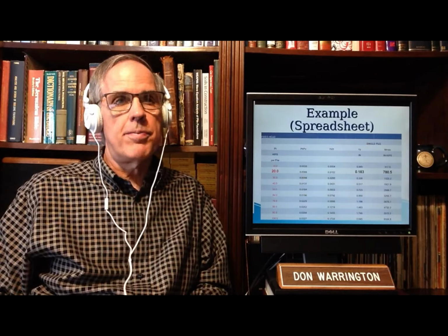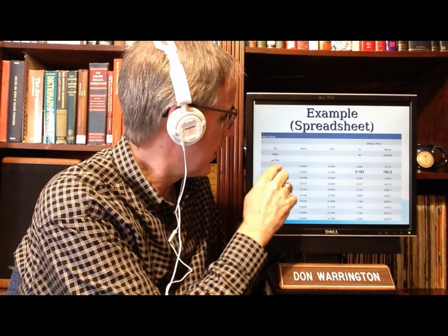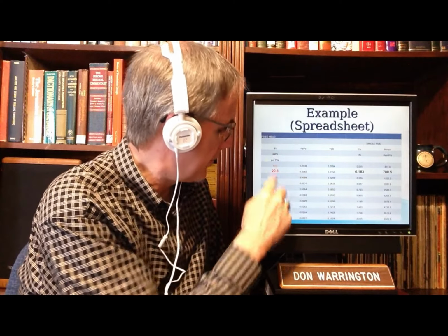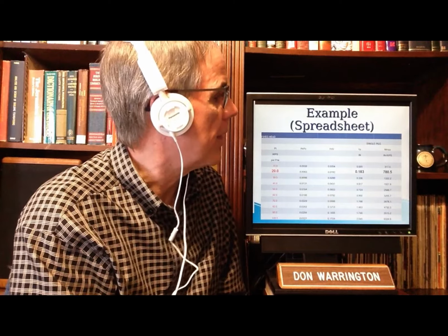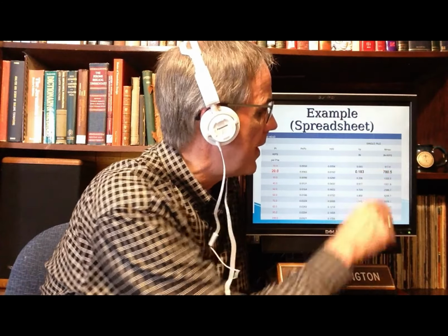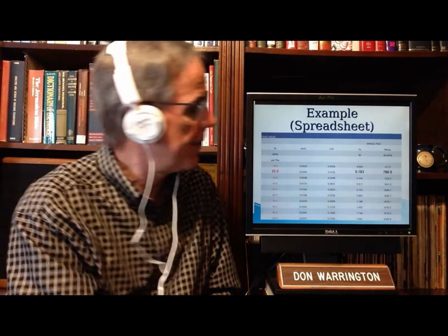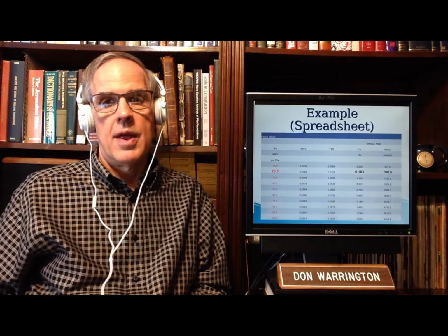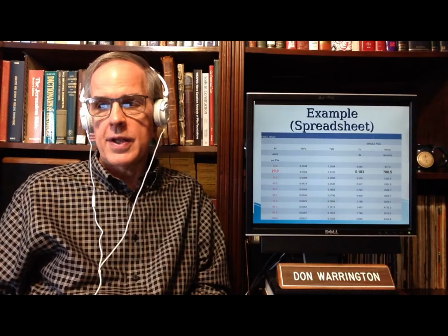All you have to do is pick one of those, substitute whatever loads are over here, and then you read across. In this case, I picked 20 since it's one of the ones that was given, and it gives you a maximum moment of 78.5 inch kips and a YP, which is the deflection at the pile head, of 0.183 inches. That's pretty much it. The only thing you have to avoid is misreading the spreadsheet.